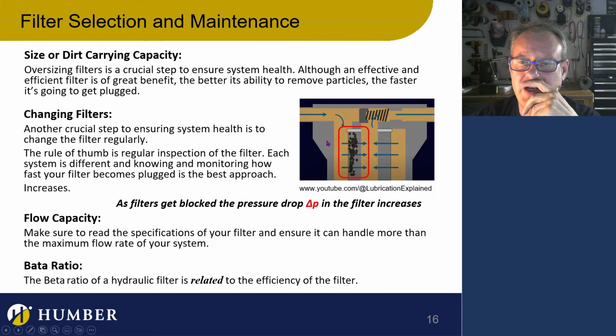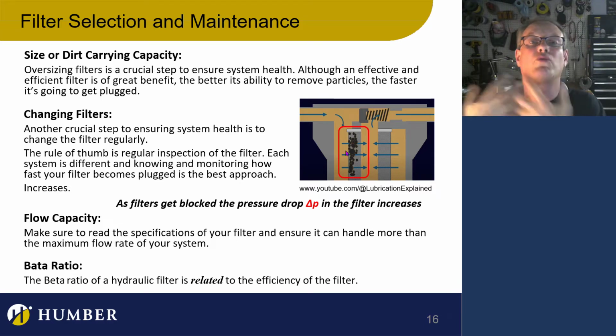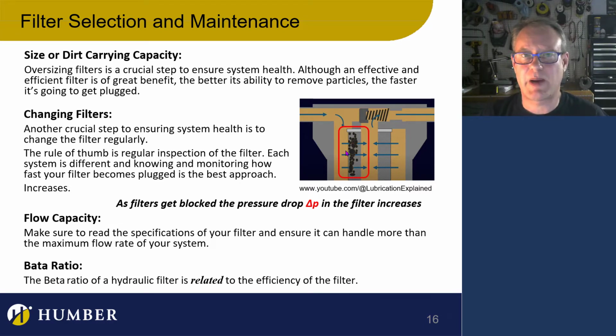But for now, I just want to say that the dirt carrying capacity of a filter is really very important. You want to make sure that you overrate the dirt carrying capacity of the filter. When you're choosing a filter, it will show you its dirt carrying capacity. There are some other attributes that we'll take a look at, but essentially, it's really important. And the dirt in itself, let's just say there's a perfectly clean filter.